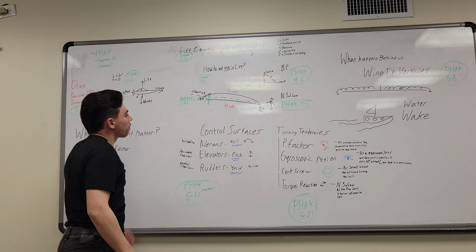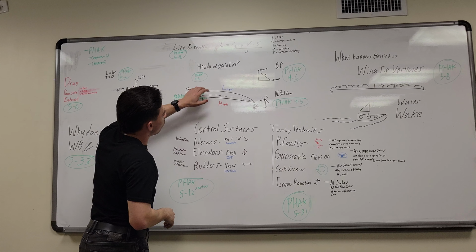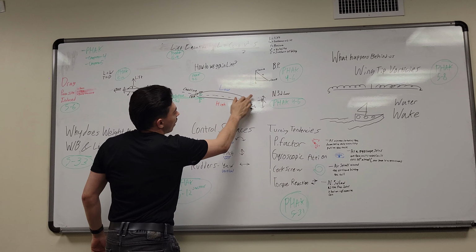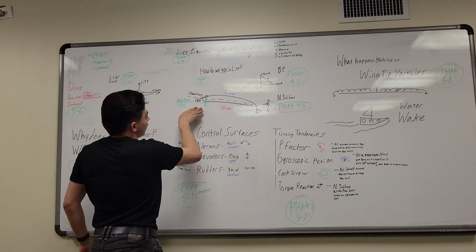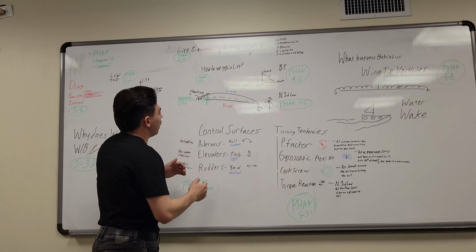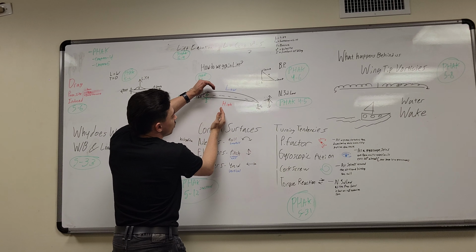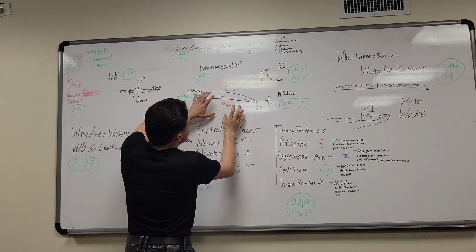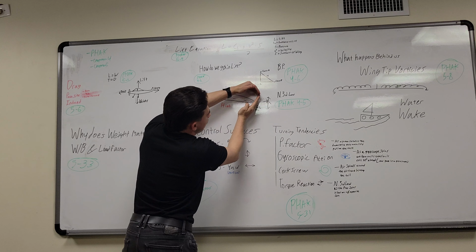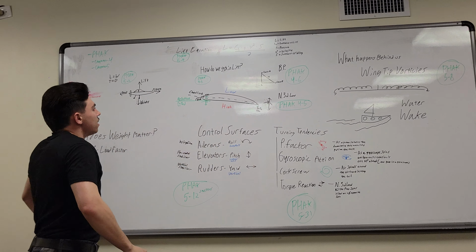Applying this to our airfoil, the wind's going to be hitting that leading edge. Some of it's going to be going over the longer end, having to travel faster, creating lower pressure, whereas the wind under it is going to be going at a nice smooth pace, staying at a high pressure. Air always wants to be at equilibrium, so that high pressure is going to be pushing up on the airfoil, trying to get to that low pressure, generating lift as they all meet at the end. So that's going to be how we gain lift.